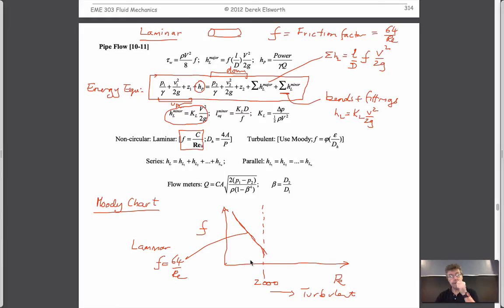And so we have this behavior now, which we know what to do with, but we've made this point that it's really only for the simplest case that we could imagine. And the simplest case is where we have laminar flow, the deck of cards. One lamina of water sliding over the other one, so that when you look at the behavior in a cross-section of a pipe, then you get this parabolic behavior.